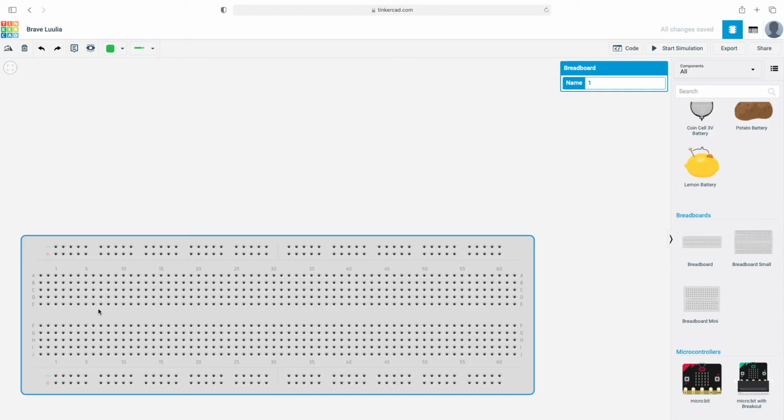Now this next section down here, all of these tie points are connected vertically. Now from one vertical row to the next, these are not connected, but again, connected vertically. And this next section is the same way. And then this bottom section behaves just like the top. Again, these tie points are connected horizontally, but not vertically, between these two horizontal strips.